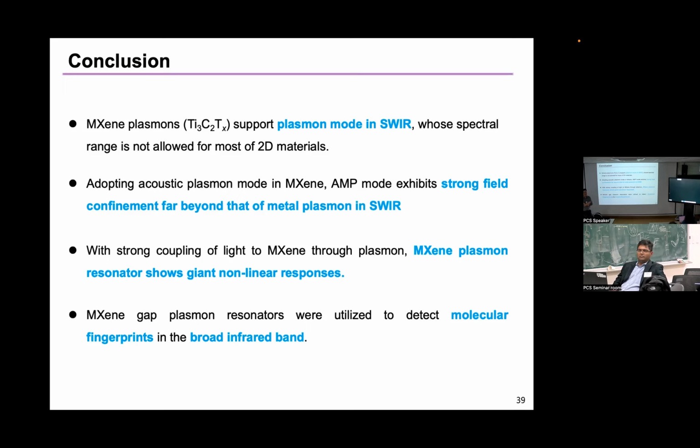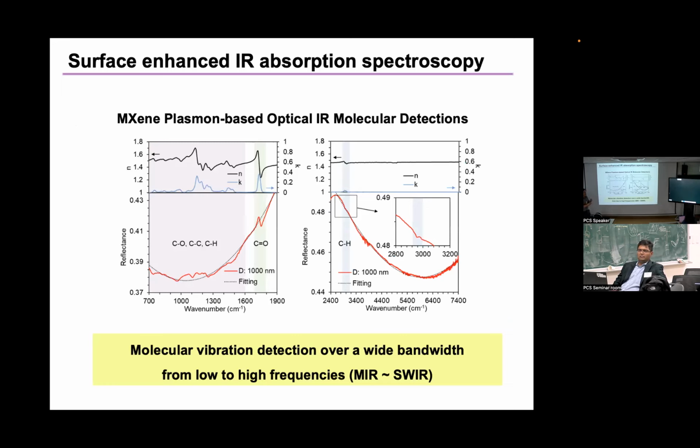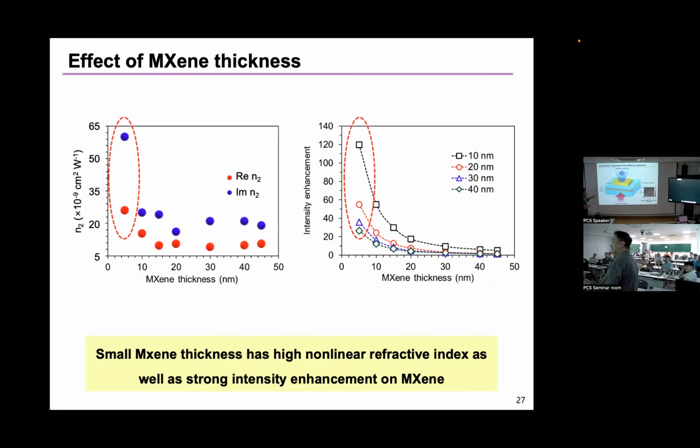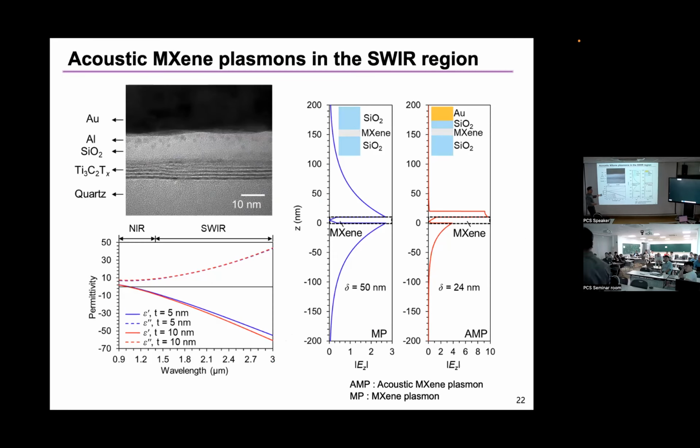That's a very good point. We are still working on the theoretical analysis of the MXene structure. It's quite difficult for us. So in this study, we just use the final values of the permittivity. This permittivity includes all the properties. These are ellipsometry measurements, right? Yeah, ellipsometry measurements. And you're basically using it as a continuous medium. We just changed the thickness. But within the thickness, you are modeling it as a continuous medium, right? Yeah, sure. So 5 nanometers is fully continuous. That's how you're modeling.